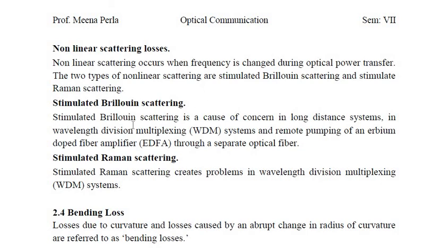The stimulated Brillouin scattering is a cause of concern in long-distance systems, in wavelength division multiplexing systems, and in remote pumping of an erbium doped fiber amplifier (EDFA) through a separate optical fiber.